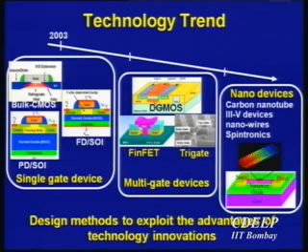Now, under such a scenario, you can do all kinds of things. Who says that the back gate has to be similar to the front gate? The back gate can look different from the front gate, right? You can put in a back gate bias, which can be different from the front gate bias. So you can do all kinds of interesting things there and come up with interesting circuit topologies and so on. But anyway, people have started looking at those, and there's a possibility that if you look at a 15 nanometer device, you might have to go with a double gate device from the scalability point of view. But again, remember the most important thing here is the scalability of these devices. Those are better scalable than the single gate devices.